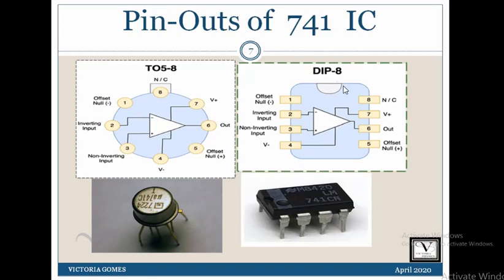The pin numbers can be easily identified by holding this IC with the pins downward, and the identification mark or the cut mark in the forward direction as shown in this figure. There may be a dot as well. This is pin number 1, so you can find a dot near pin number 1 as well.